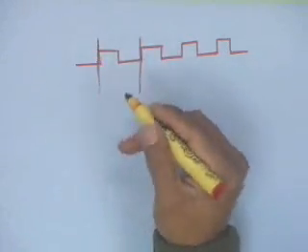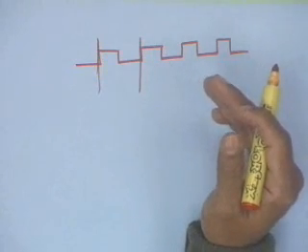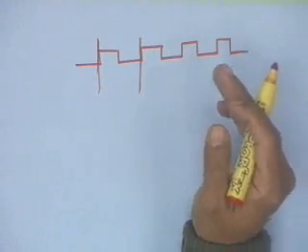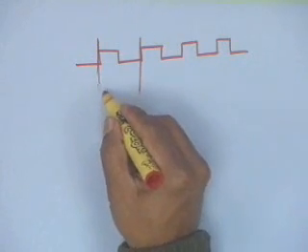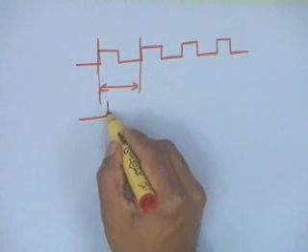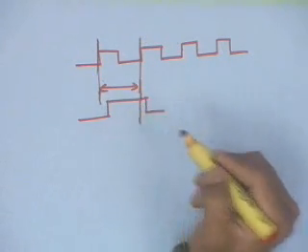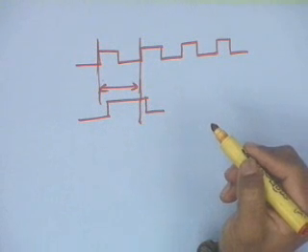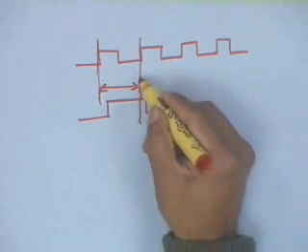What I am assuming is all actions, all state transitions, all loading, everything is taking place at the rising edge. You can assume everything at the falling edge will remain the same. So during this time, there is going to be a certain microinstruction. And if I give a load signal, the load is a synchronous load, and at the end of this cycle, the loading will be performed. All loads are going to be performed.